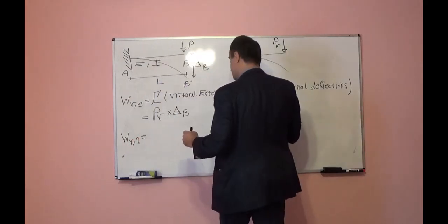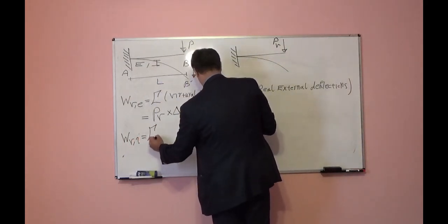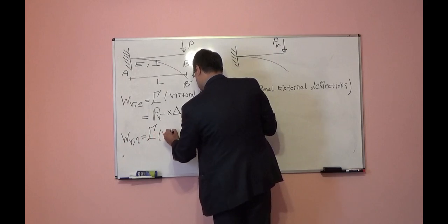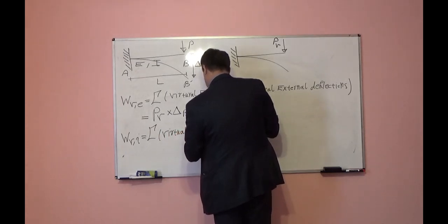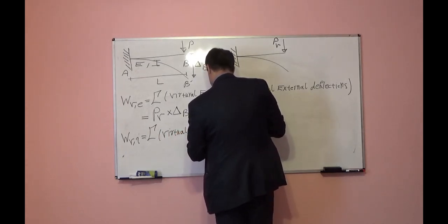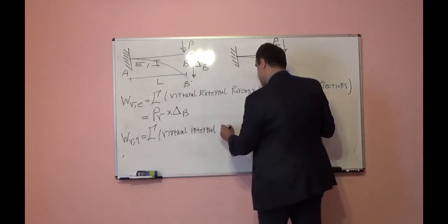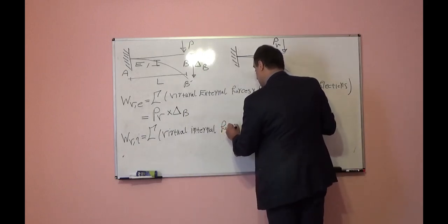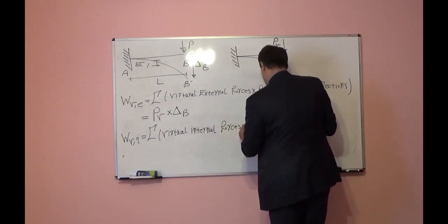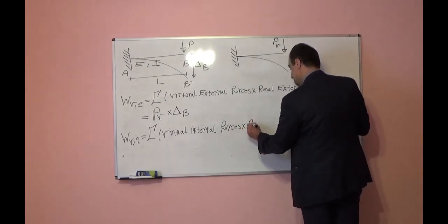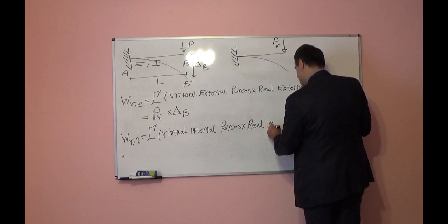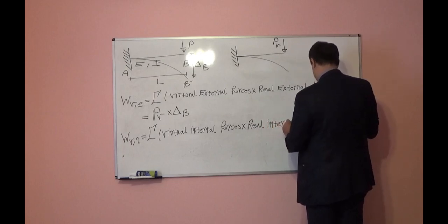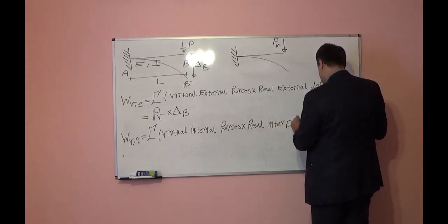Internal virtual work will be virtual internal forces times real internal deflections.